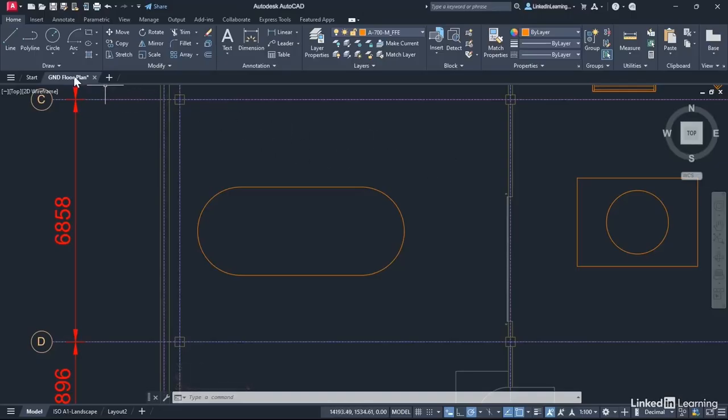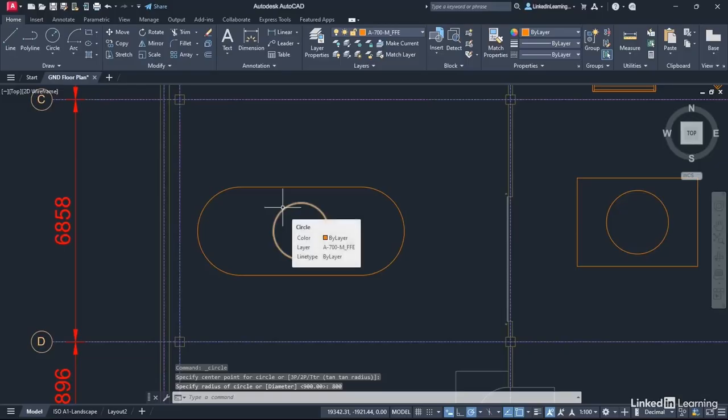We'll go to the circle command now and center radius on the fly out there. Hover over this midpoint snap. Don't click on it. Hover over this midpoint snap. Don't click on it. And as you come down, as you can see, we get the intersection there of the polar tracking lines using our object snap tracking. Left click, drag out for our radius, and we'll type in 800. And there you go. There's our 800 radius circle in the center of our table.